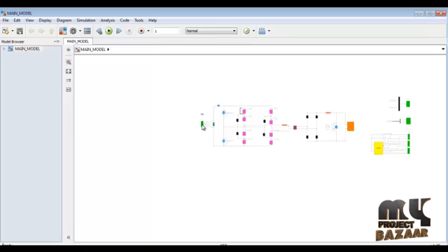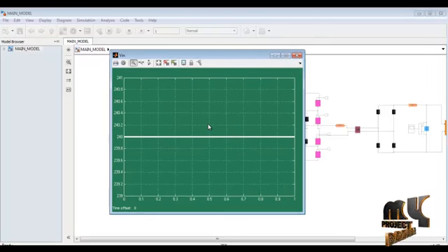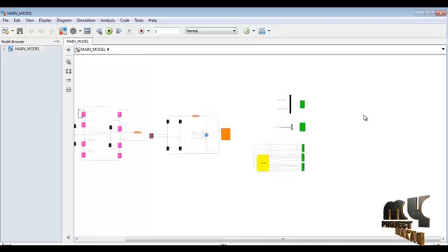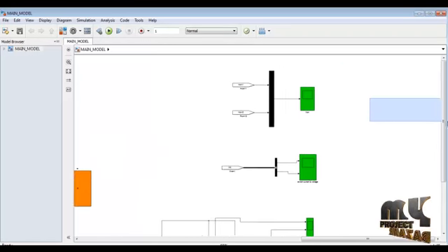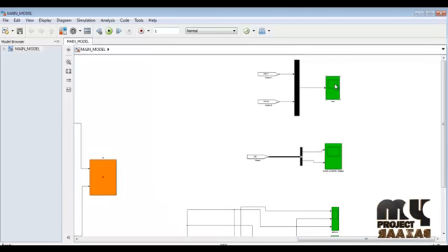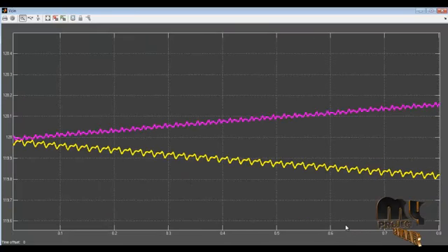This is our DC input. We give a constant DC input of 240 volts. And next we can see the corresponding scope blocks using the From and Goto functions. This is for VCN, because this is the flyback converter voltage. We can use the zoom axis button and click on those specific blocks to get that result.